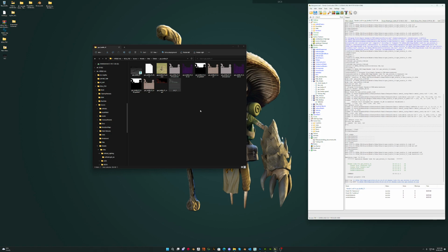One thing you can notice is the palette V file. If it's got a black and white image in there, you know that the palette's working really well, and it's been picked up and identified. Once you've generated your LODs, as you can see, we chose 512 for LOD 1 and 128 for LOD 2, so it's generated the files respectively compared to what we actually chose within the options of the set object properties. Because we've just generated the LODs, we need to reread and build the library again.